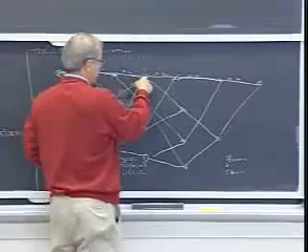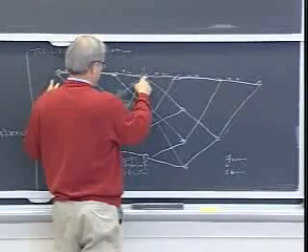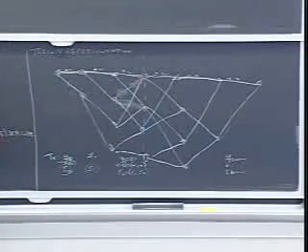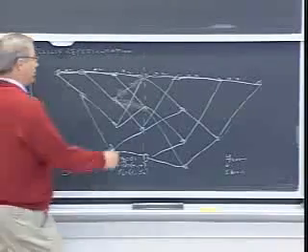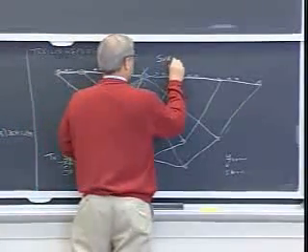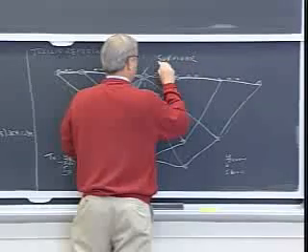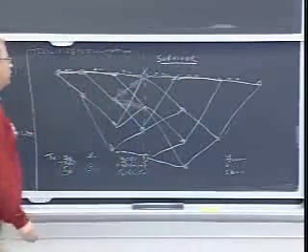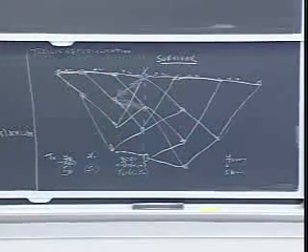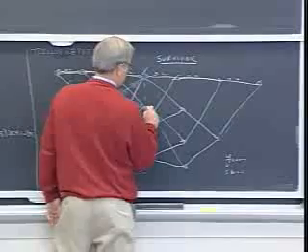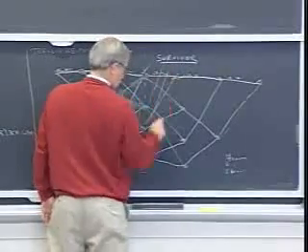So at this point, I can make a decision between all the paths that get to that node and pick just one, the best one that gets to that node. And that's called the survivor. This is really the key concept that Viterbi introduced. All right? We only need to save one, the best up to that time. We need to do it for all the 2 to the nu possibilities.